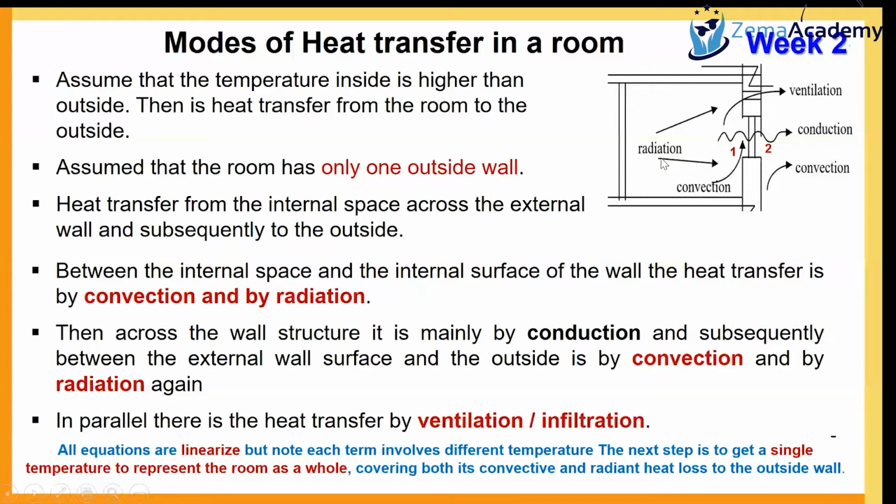When we came up with all these equations for this one room model, we realized that there were two things that need to be considered. The first thing was that all those equations were not linear. For example, the conduction was linear, whereas the radiation and convective heat transfer equations were not linear.